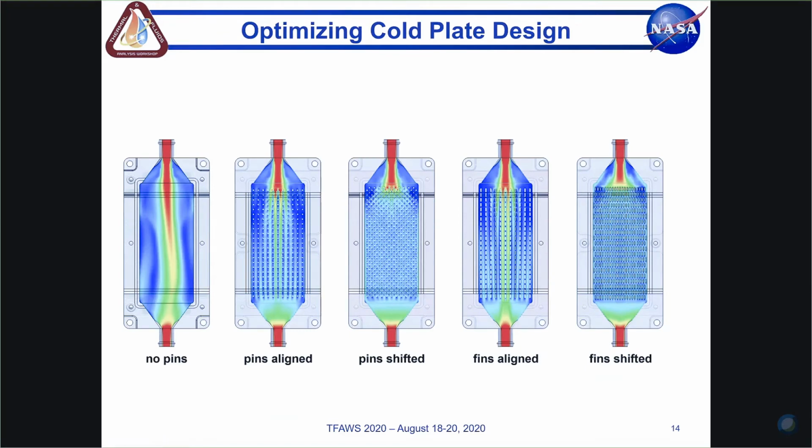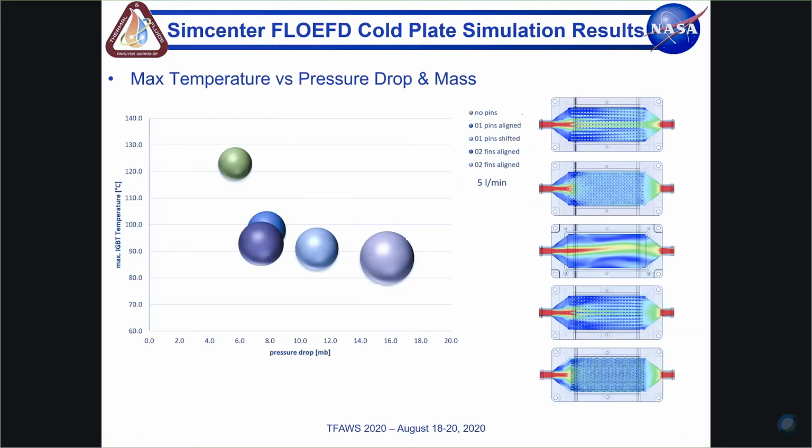Now, for the parametric study that we ran, once we do the meshing once, we don't need to do it again. So that study can be a little bit more efficient. That entire study took about 9 hours to solve in this particular case. And here are some nice temperature plots for you to look at. And you can see by staggering the pins, obviously we introduce more obstruction to the flow, which tends to even out the thermal behavior, but might introduce some additional pressure drop. And we'll see that in a second.